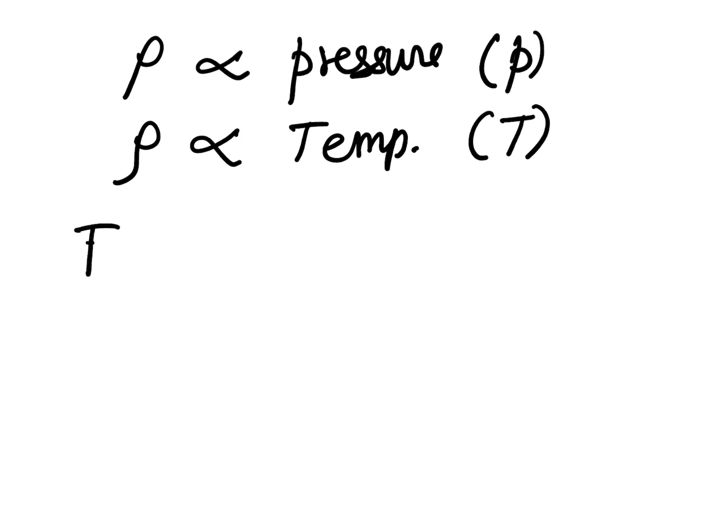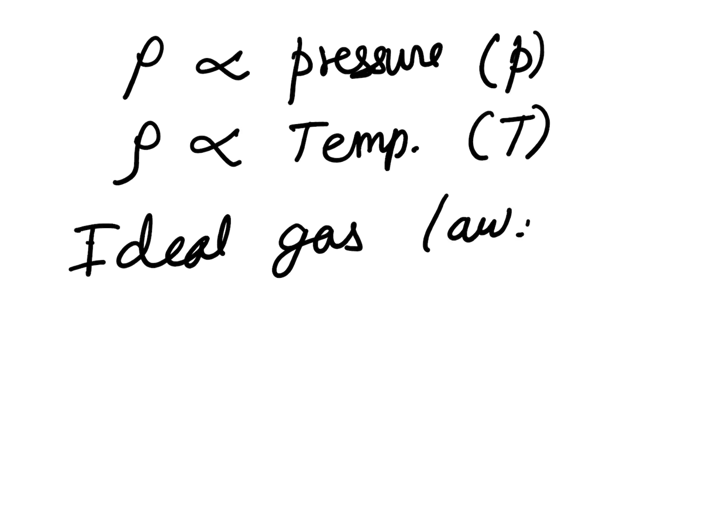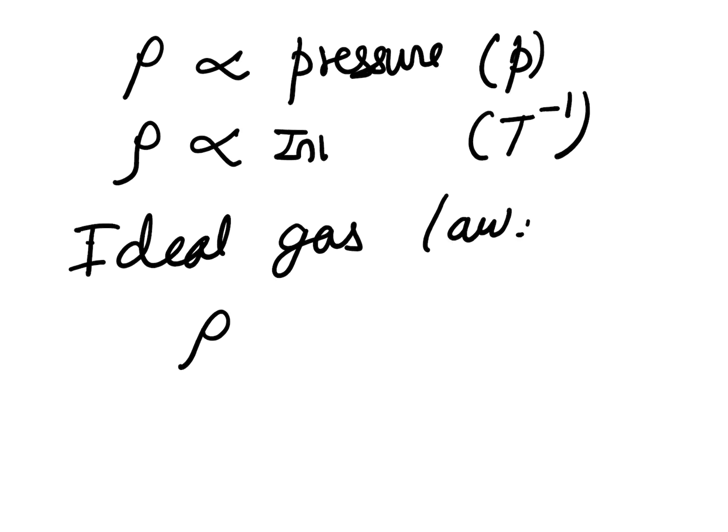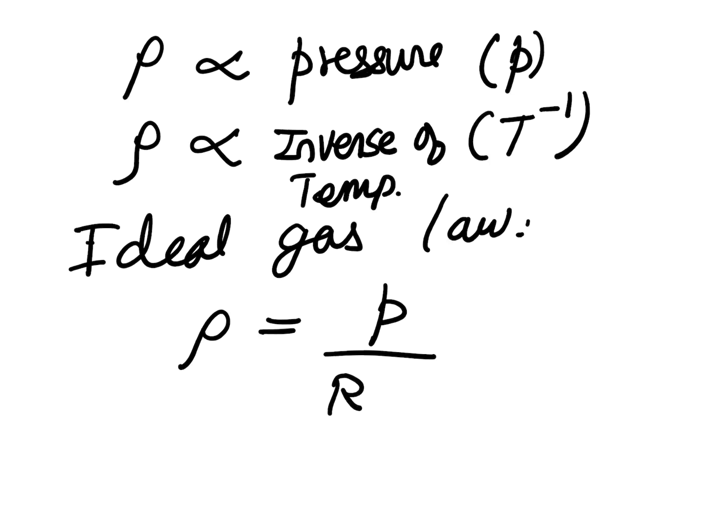We have the ideal gas law that describes how density changes with pressure and temperature. I should correct this: it's not proportional to temperature, it's inversely related to temperature. Rho is pressure divided by R T. This is called the ideal gas law.